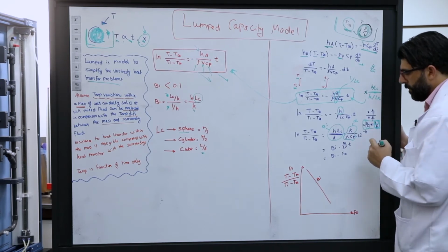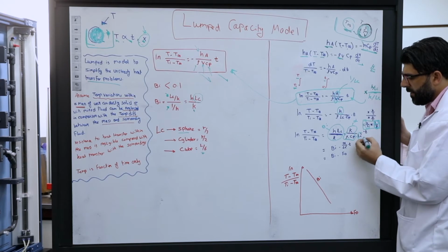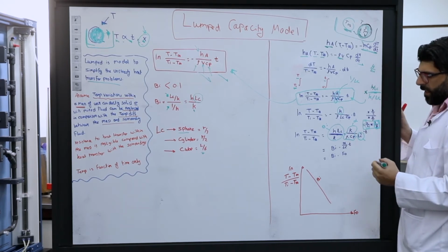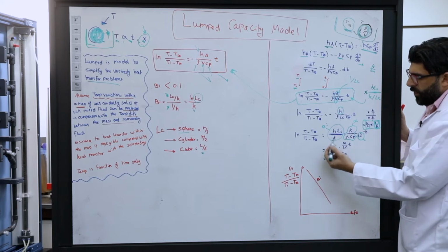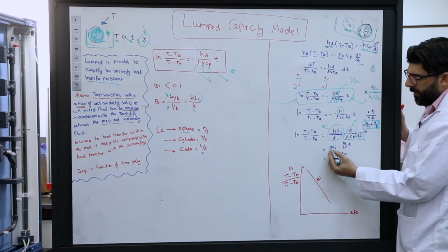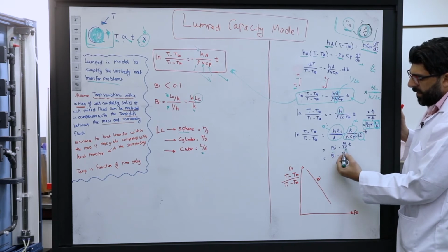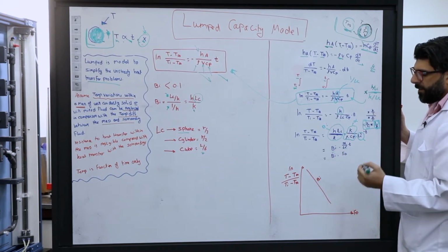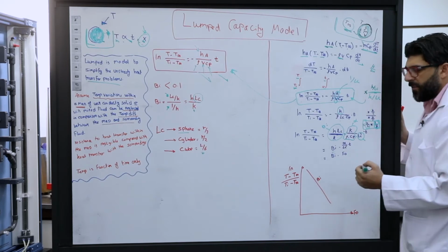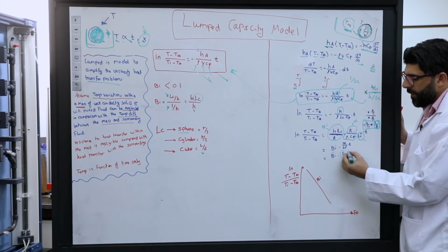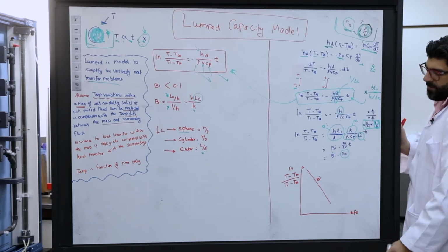And this is the squared characteristic length. So this equation can be written as Biot number times alpha over LC squared times T. And from the heat transfer definition, alpha over LC squared times T is equal to the Fourier number. So this is the Fourier number.